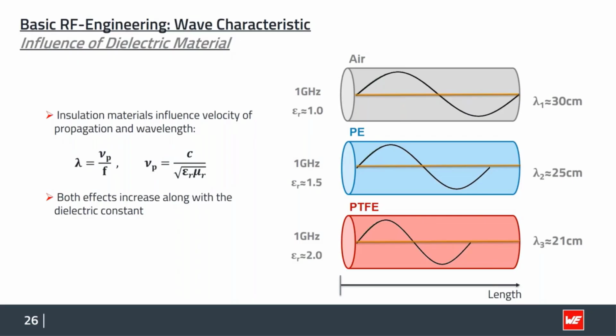And this is really crazy in a first thought, but this is explaining why we really have issues when we change the material. So if we go from a PTFE material in the cable to the PCB with FR4 material that has a different epsilon R, then we will stretch or bend our wavelengths. And this is, of course, what is causing trouble and reflection and loss of energy.